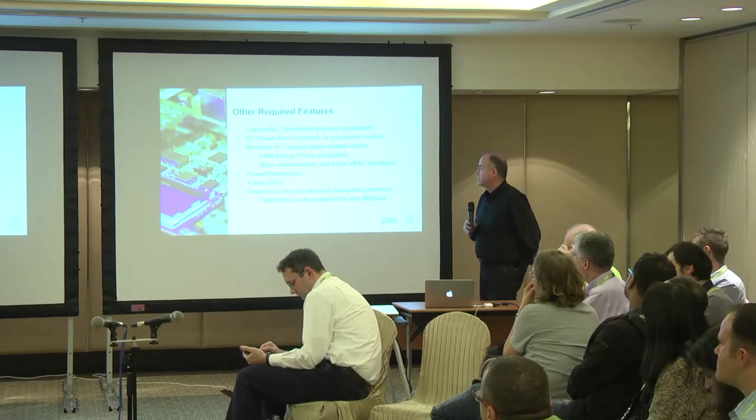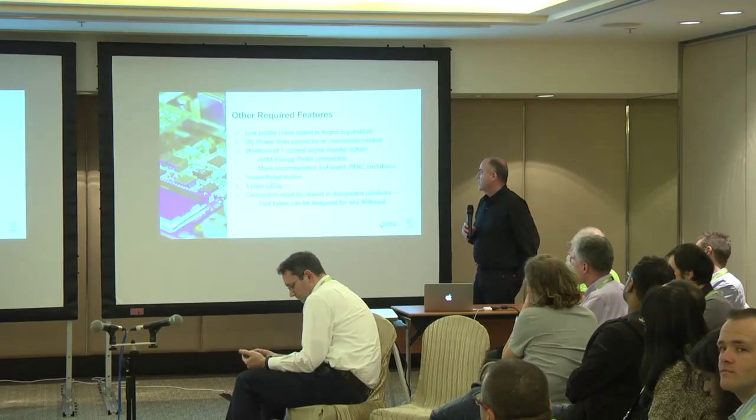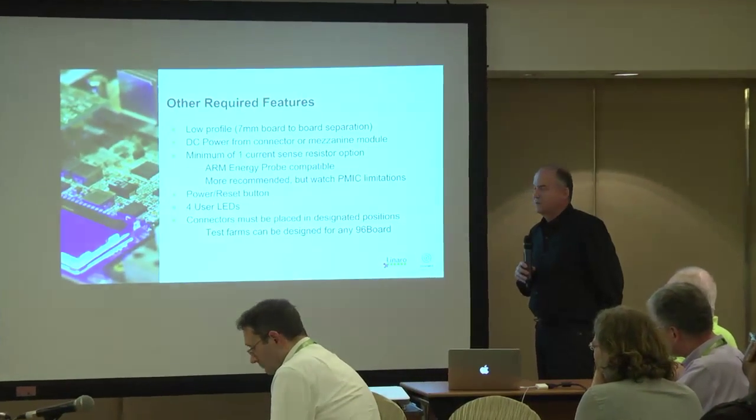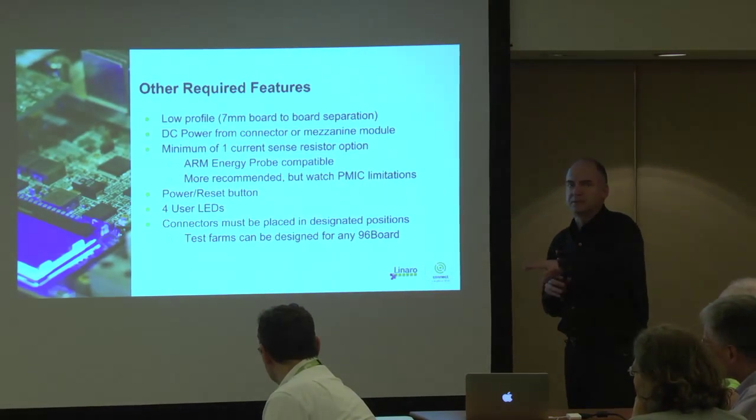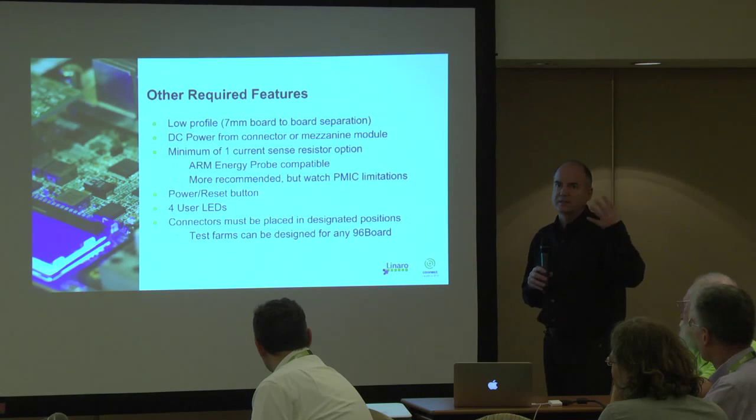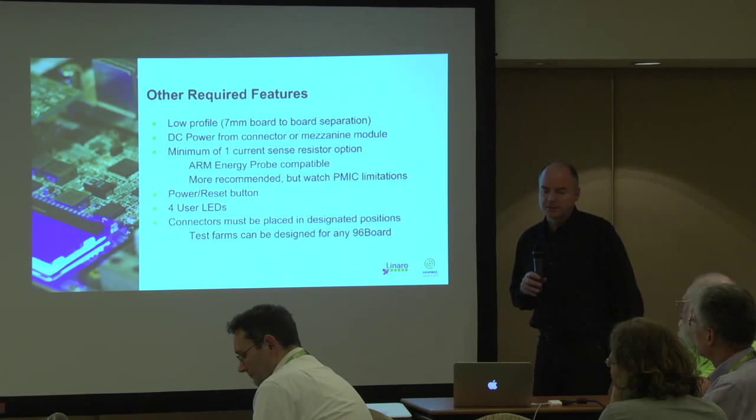You've got to have a power reset button, you've got to have some user LEDs, and the connectors must be placed in the designated positions for 2 reasons. One, obviously, for compatibility between different boards, and the second, so that we can easily design test farms to put all of these boards into.